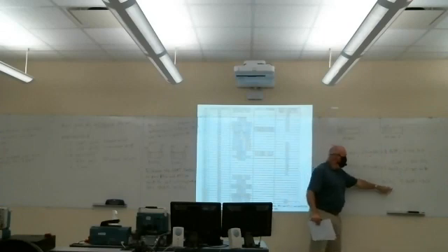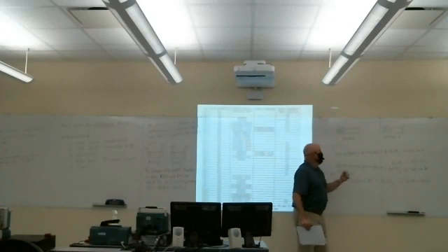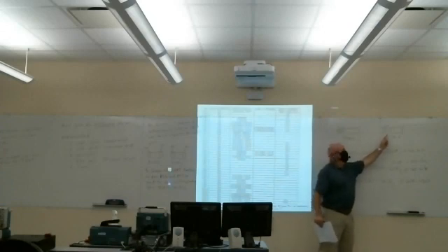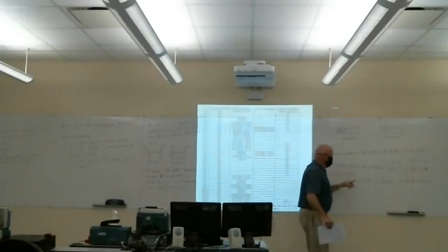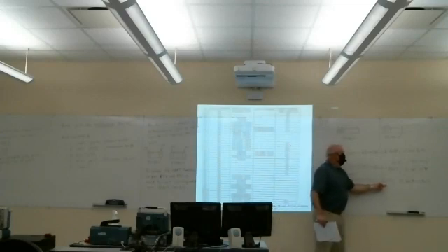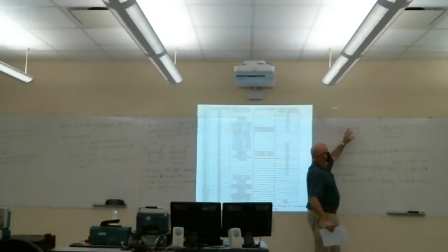But why write C0 instead of 3F? Well, I want to think about the bits I'm changing. It's only bit 7 and bit 6, and if I think about only those 2 bits and everything else being 0, then that would correspond to C0. And so by doing it this way, I'm not having to write this out and say, well, I need ones here and zeros everywhere else.